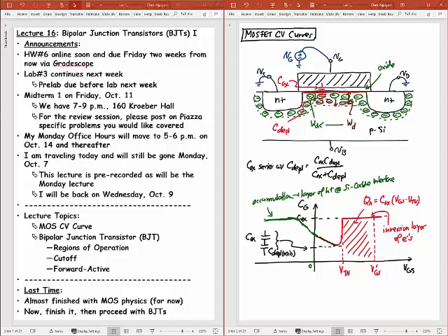Okay? And so this is what the capacitance versus voltage curve looks like when you're just looking between the terminals VG and either VS or VD going to ground there. And when you think of this capacitance, what I'm basically saying is that this Cox looks like some static dielectric, but for this C depletion, the dielectric can move. But for capacitance, what you really need is an AC signal across that.